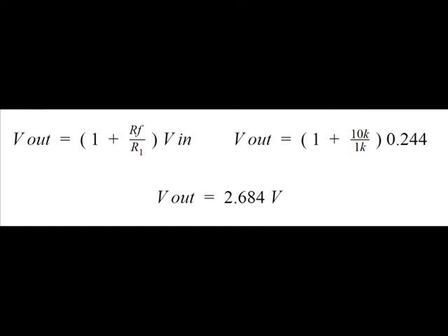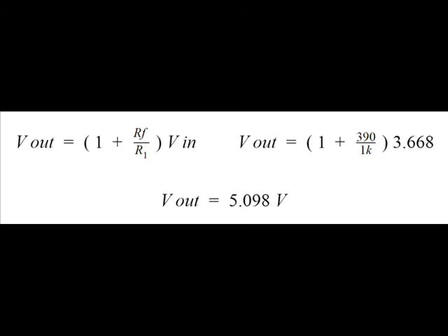Applying the formula, we increased the output voltage in the secondary winding. At the rectifier output, the amplitude is the same, so the voltage increases less. After the filter, the input voltage in the last operational amplifier non-inverter, the oscilloscope measured 3.668 volts. To reach the voltage range, we apply a non-inverter configuration to increase the input voltage.